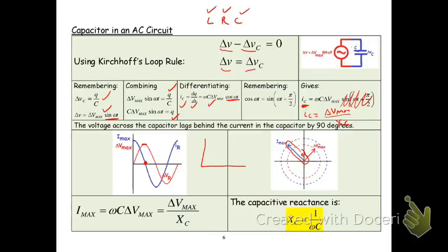So now if I do ohms versus omega, I get the inverse relationship. The capacitor kills you at low frequencies. If a radio station is trying to drive your radio at a frequency lower than the setting of your radio, although the signal is picked up in the antenna, any current caused to flow through your circuit is pinched away by the very high capacitive reactance. So the inductor kills your high frequency stations and your capacitor kills your low frequency stations.